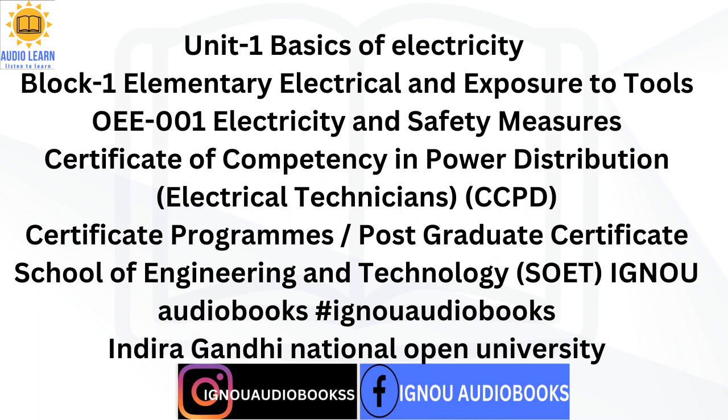1.3 Summary. We have learnt about basics of electricity and magnetism. Electricity is basically measured in terms of voltage and current. We saw the difference between direct and alternating current, DC and AC. In AC, voltage and current keep changing with time, and if we were to draw a graph, the voltage or the current would be shown as a sine wave. Ohm's law defines the relation between voltage and current passing through a material. The ratio of voltage to current is the impedance of that material or circuit. In case of steady-state DC, the impedance is the same as the resistance.